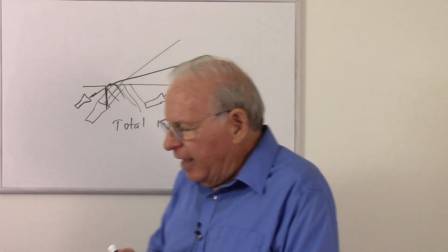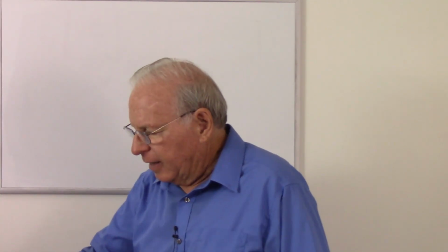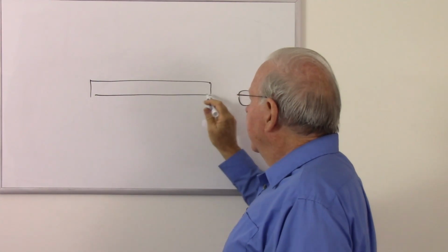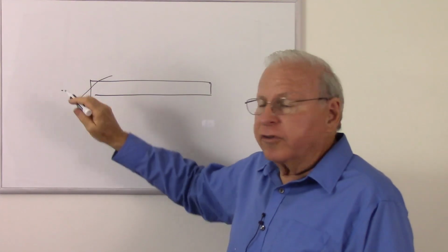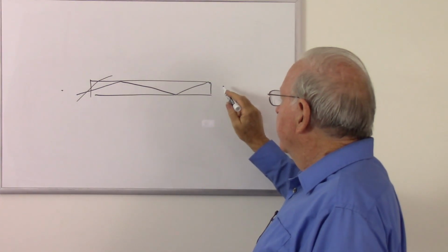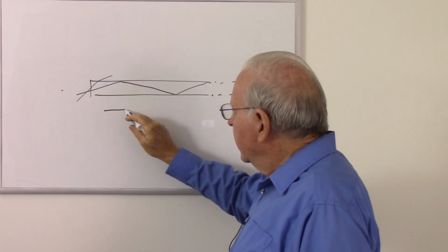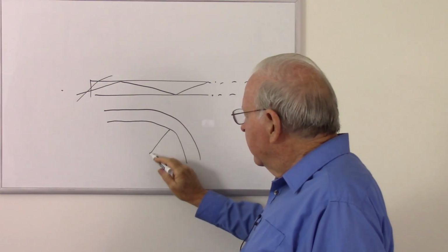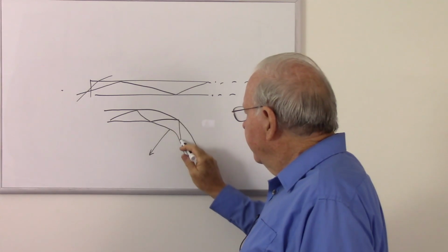So if we can make a tube of glass such as this, there's the ends, and I shine a light beam in there. If the light beam enters at a high enough angle, a lot of it's going to escape. But if the angle is low enough, 100% of that will just simply reflect back and forth, and it can go down this great distances. And also, if we go around corners, as long as this radius is below a certain radius, that light will continue to reflect inside that.